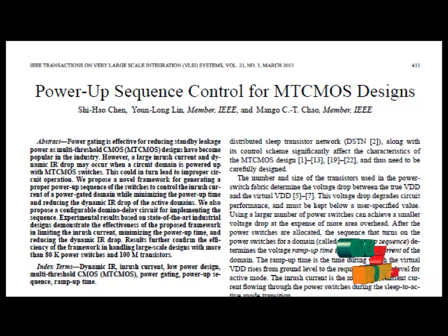The first token traveling through a pipeline turns on downstream pipelines, hiding the latency cost of wake-up in the computation time of upstream pipeline stages. Synchronous circuits cannot take full advantage of such an aggressive power gating control scheme, as local supply voltages must reach nominal values to prevent the synchronous circuit from violating its timing requirements, for example, setup or hold constraints of state-holding elements.